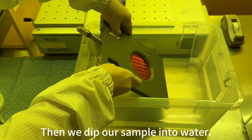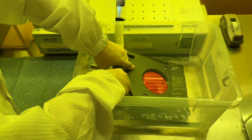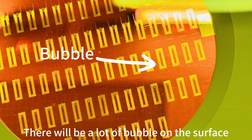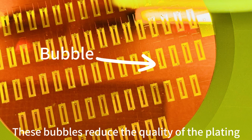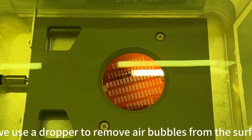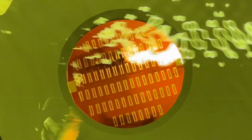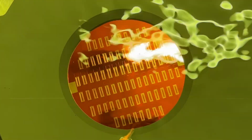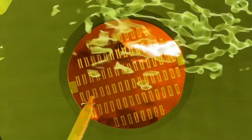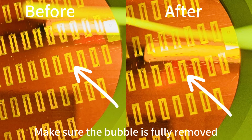Then we dip our sample into water. There will be a lot of bubbles on the surface. These bubbles reduce the quality of the plating, so we use a dropper to remove air bubbles from the surface. Make sure the bubbles are fully removed.